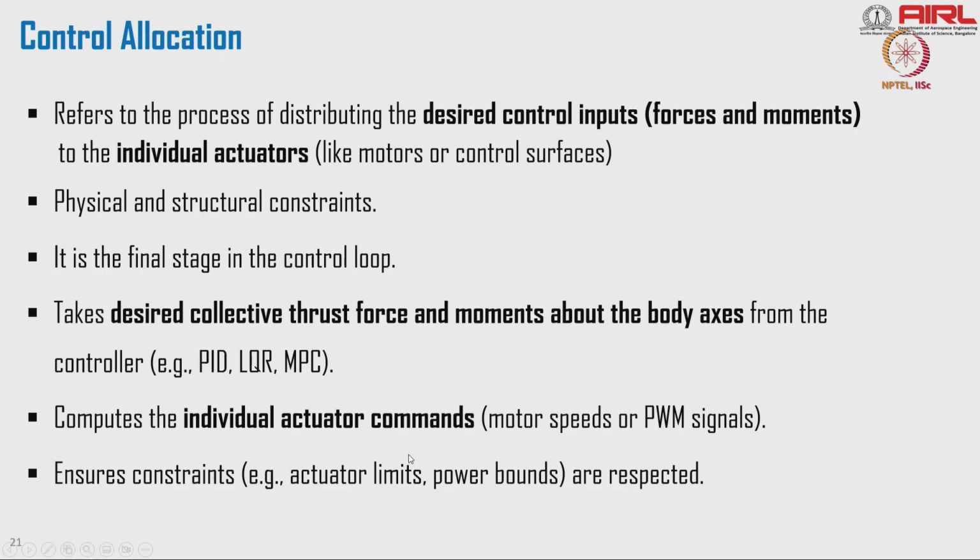It computes the individual actuator commands. It depends on how the configuration is, right? How your multi-rotor system is configured. Is it a plus configuration or a cross configuration in a quadcopter, or in a hexacopter, how has it been arranged? Is there any tilt in the structural position? It takes care of all the information and computes the control input.